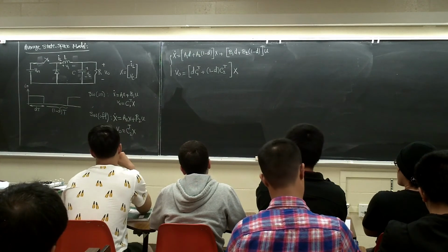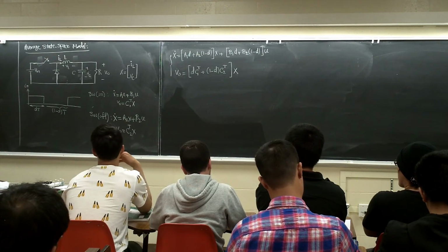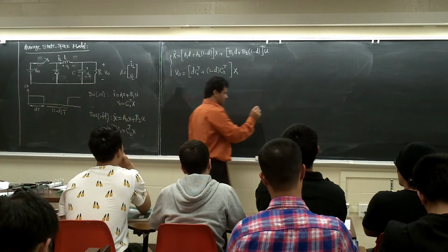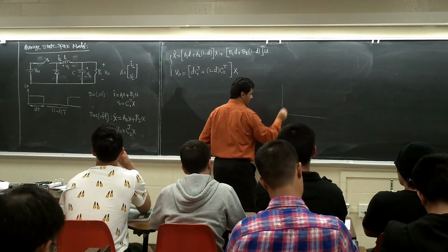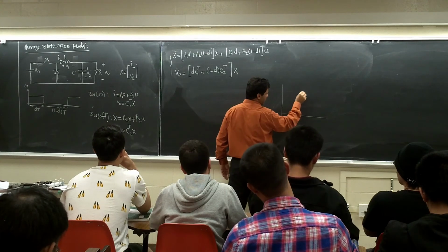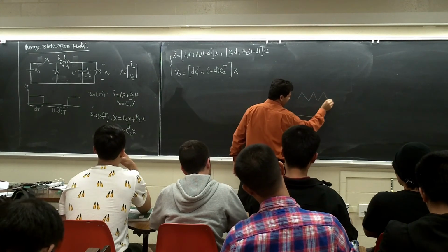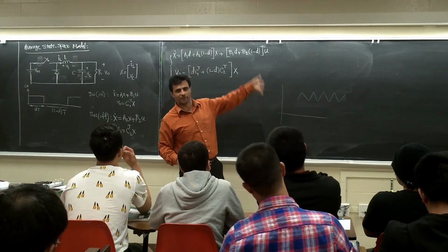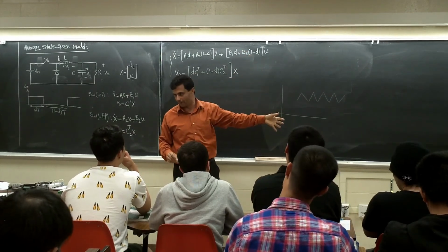You know, it's not going to be very accurate, right? Why? Let's say it's not accurate. If you look at the inductor current, think about it, in the steady state. The inductor current, remember, it was like this, right? We have a ripple on it. When it's on, it's going to go up. When it's off, it's going to come down, right?